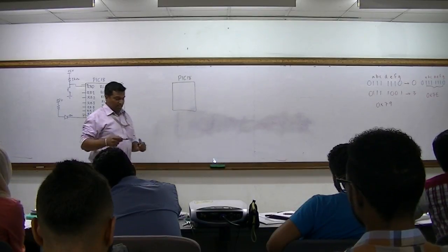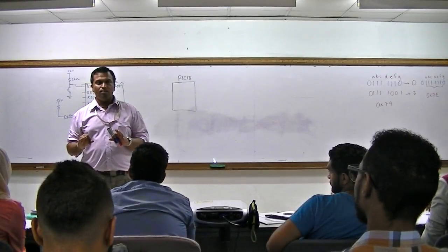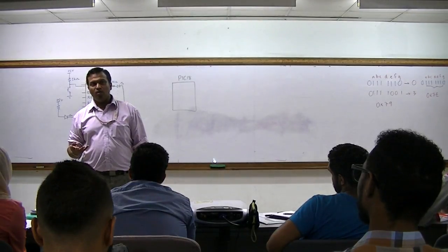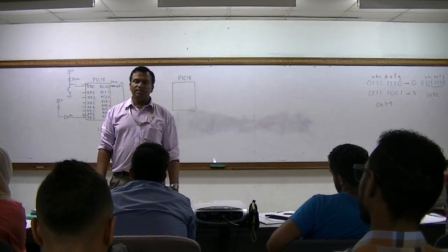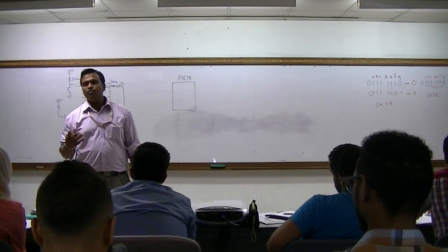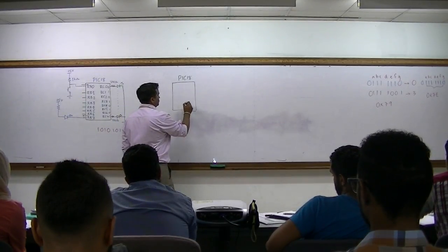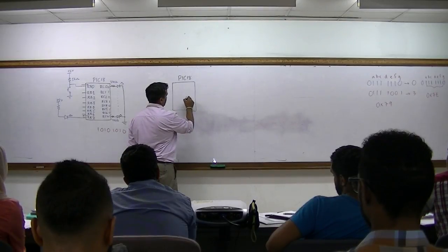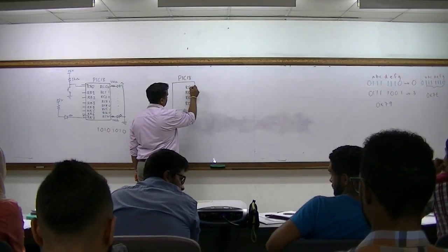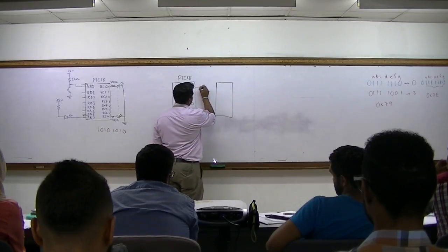So with that way of interfacing, you require 7 pins out of your port. There's another way using the BCD encoder where you only require 4. Why do you only need 4 for BCD? Because for BCD, the decimal digit only uses 4 bits of binary code. So you can use this, 0, 1, and so on, only 4 pins.